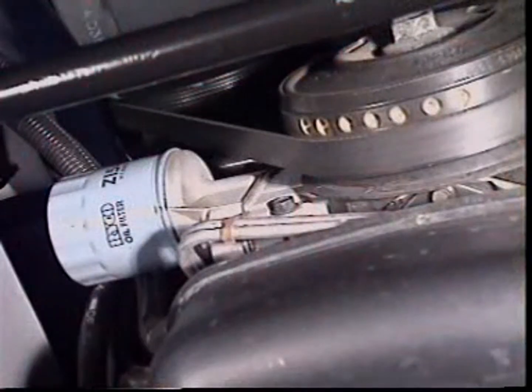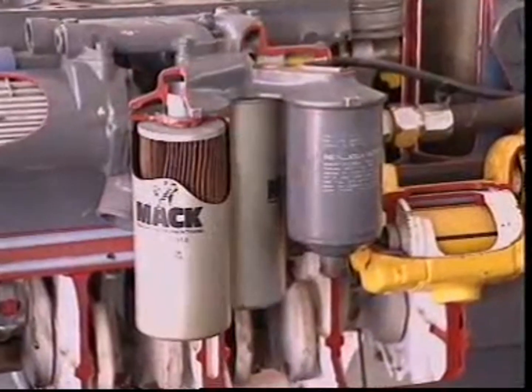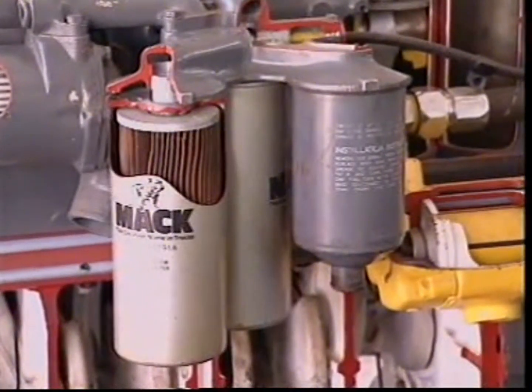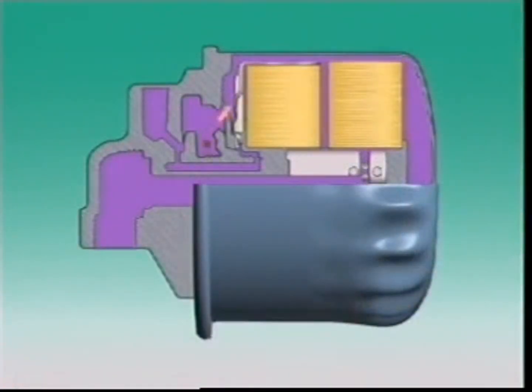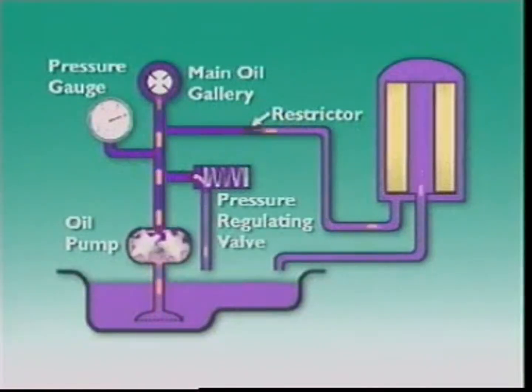Most oil filters on diesel engines are larger than those on similar petrol engines, and some diesel engines have two oil filters. Diesel engines produce more carbon particles than petrol engines, so the oil filter can have a full flow element to trap larger impurities and a bypass element to collect sludge and carbon soot. In a bypass system, the bypass element filters only some of the oil from the pump by tapping an oil line into an oil passage. It collects finer particles than a full flow filter. After this oil is filtered, it goes back to the sump.